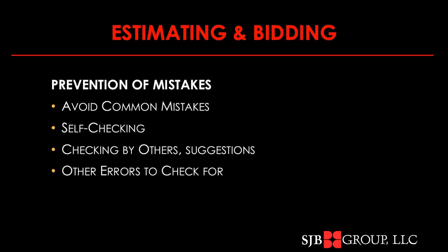Some other errors to check for. You're going to check that all numbers were properly transferred. You're going to check the scope of work. Is your written estimate consistent with what you thought of the work as you began to do your takeoff? You're going to be looking for math mistakes. Again, don't rely on your calculator without a tape. Don't rely on the calculator without your thought process saying, is the result reasonable or not? If you're adding 3 or more numbers, get that calculator with tape or else the spreadsheet.